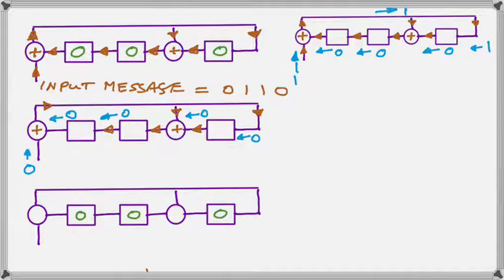But we can see what is happening when we feed in the 1. When we feed in the 1 now, we have a 0 combining in the XOR with a 1, and therefore we have a 1 along the upper taps, and after the register shifts, that 1 is going to shift in there, and the 0 is combining with the 1 to produce a 1 that will shift in here while the 0 shifts out.